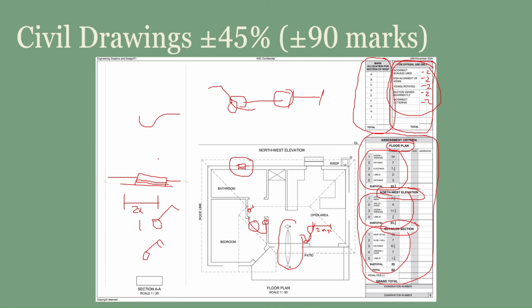Then when it comes to hatching, remember hatching is done double line, spacing, double line, spacing, double line, spacing in all the walls, your interior walls and exterior walls, load-bearing and non-load-bearing walls, all around the floor plan. And if you look at the floor plan, you see that the hatching only counts 3 marks, although it's going to take you long. So maybe I'll do this lastly.